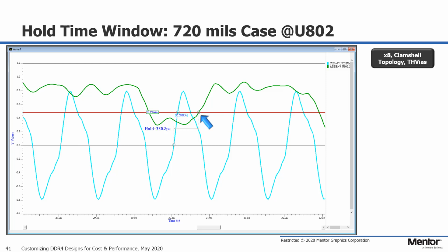the 650 mils case. As I've demonstrated, designing the address bus is more involved, especially when more loads are added to the already complex topology. By changing the lengths between the DRAMs, you're controlling the reflections more than matching the delays. Of course, there are many cases you should look at to maximize your margins, but due to the time constraints, let's look at the data bus next.